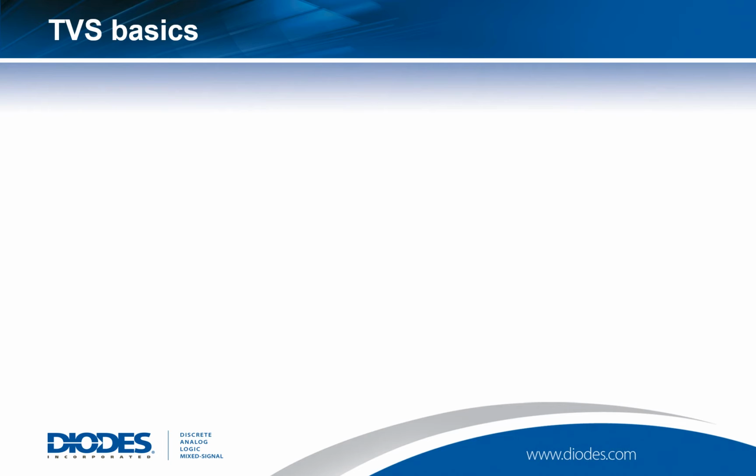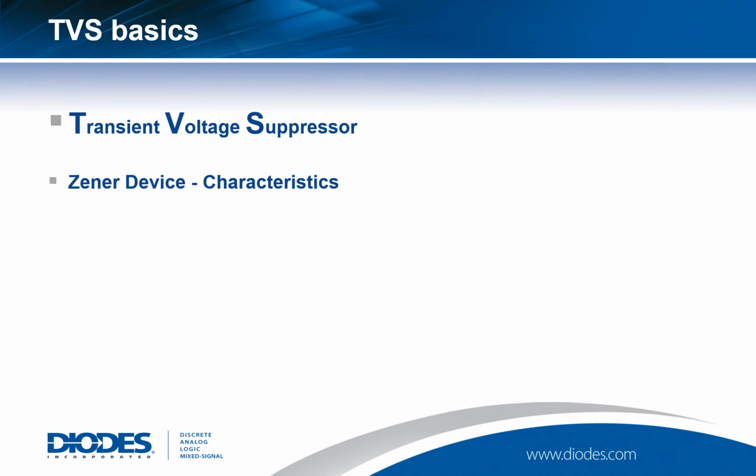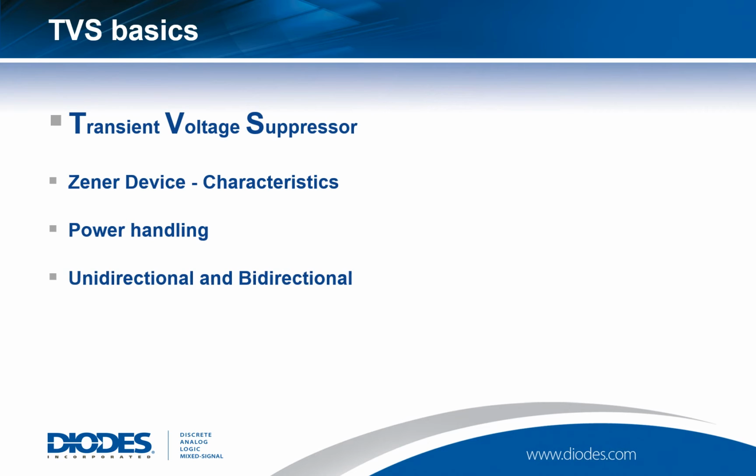So to begin with, let's have a look at the TVS, the Transient Voltage Suppressor. Now here the clue really is in the name as to what this does. It suppresses voltage transients. It's a Zener device, and we'll understand some of the characteristics that you might see in the datasheet. Let's talk about power handling, the difference between unidirectional and bidirectional devices, the capacitance, and some of the ways that the devices are packaged together.